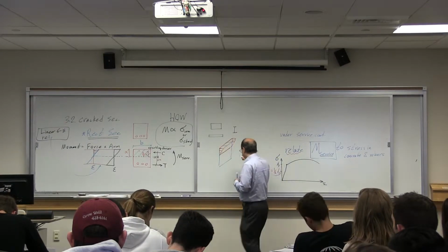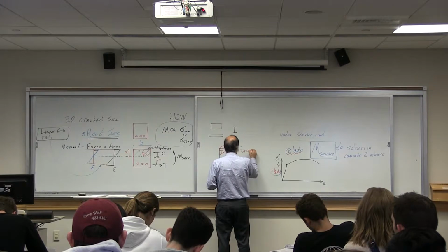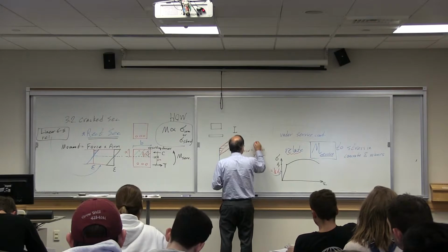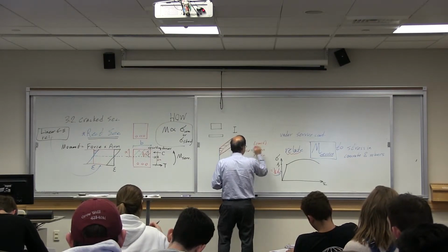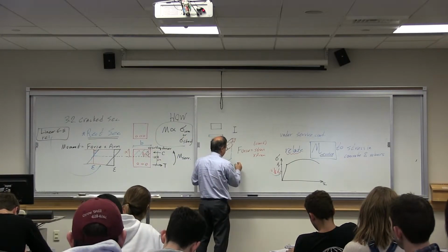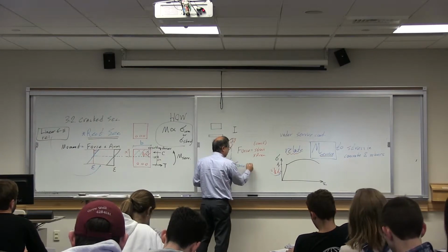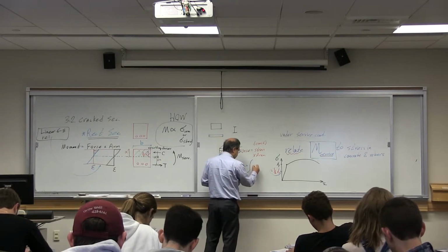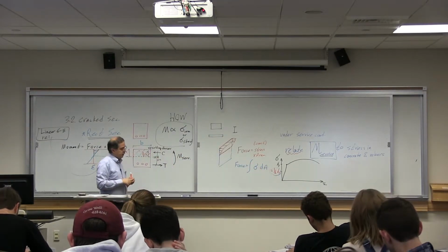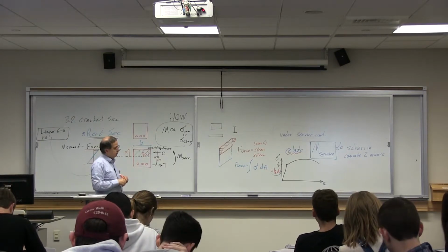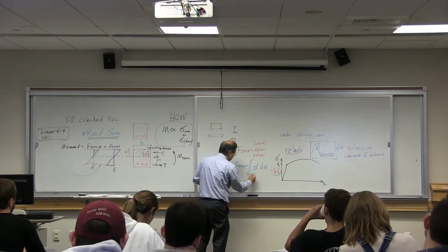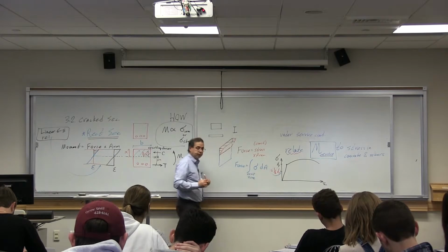Why? Because force is stress times area in general if stress is constant. In this case, stress is not constant. Therefore, force is equal to the integral of stress times incremental area over the compressive zone.